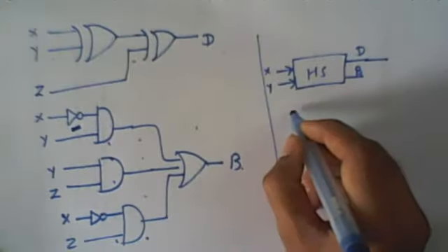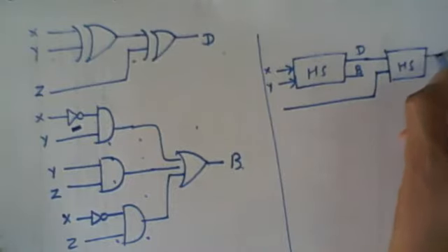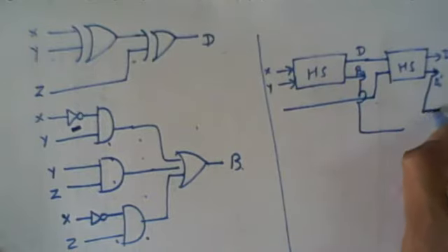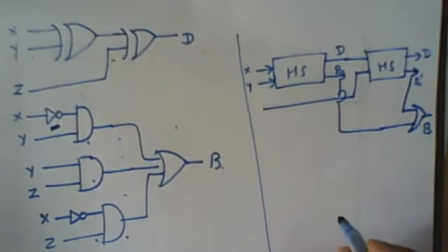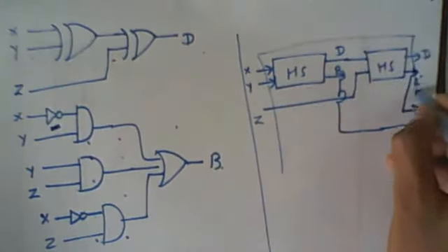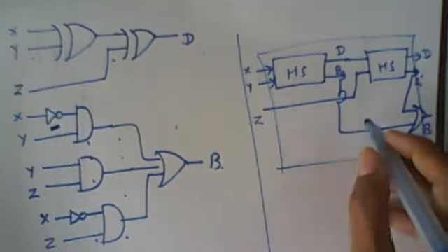The difference is again produced by the subtractor using another half subtractor, which produces the final difference and a borrow from the second one. The borrows of both the first and second will be ORed to produce the final borrow of the design. So using half subtractors we can also implement the full subtractor, using two half subtractors and an OR gate.